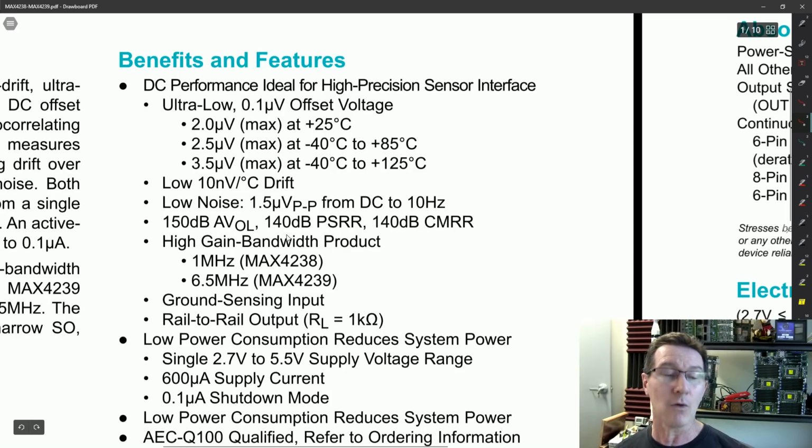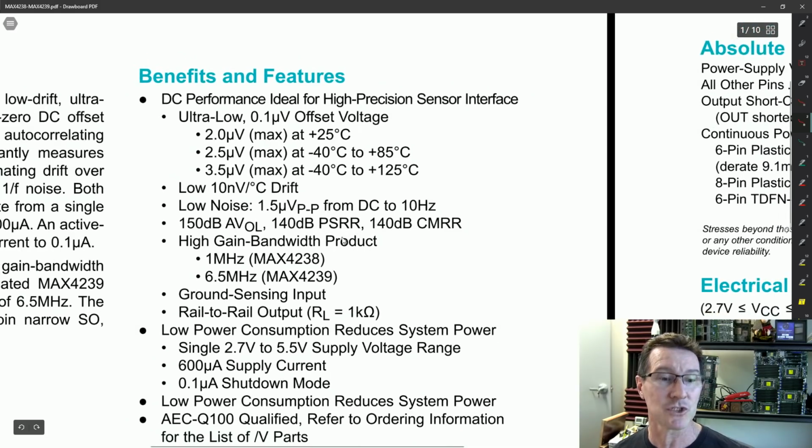So you might want to go, oh, I found this chip, but it's got 0.2 microvolts typical, but its bandwidth is like 20 megahertz or something. You might want to go, bandwidth, yeah, I think I'll live with the higher offset voltage on my product if it means I get a much higher gain bandwidth or total bandwidth of my product. So you just be willing to negotiate in your specs when you're searching for parts.